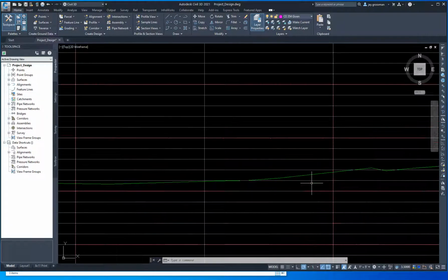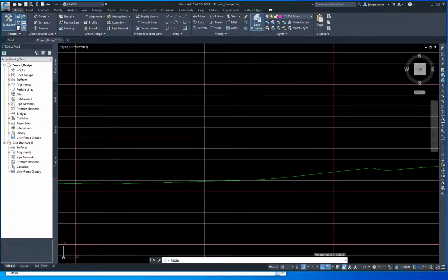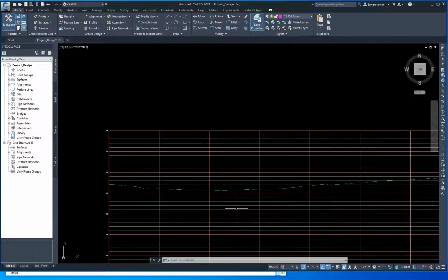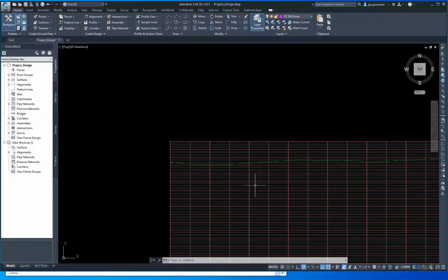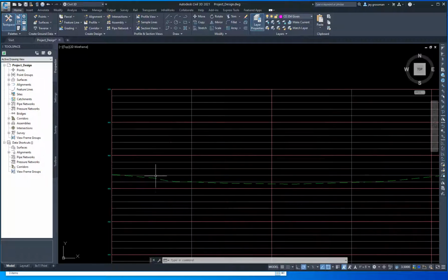And this line, I'm going to do a command called regen, R-E-G-E-N. Just type it in, it pops up, and hit enter. It's going to regenerate it, which, to save time, AutoCAD does not redraw things as you zoom in and out until you type regen. So this line should have been a dashed line all along, just to make sure you know that it's existing. Things that are dashed normally mean they're existing. Things that are solid mean they're proposed. They're new stuff. That's how we normally do drawings. So this dashed line means this is the existing ground. I just told you it was, but now we can make sure we know it's existing ground.